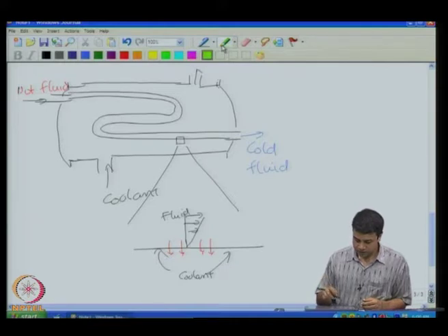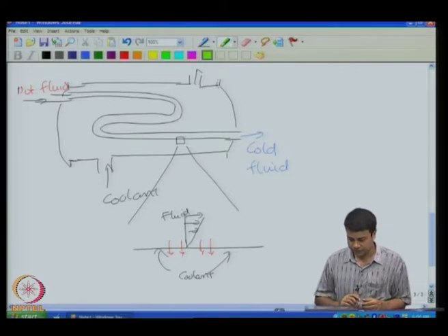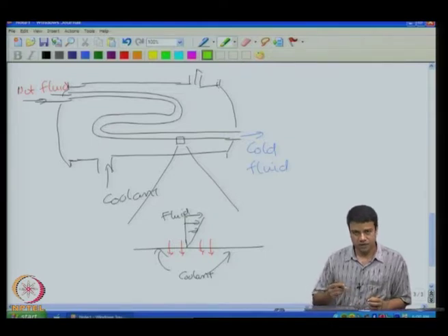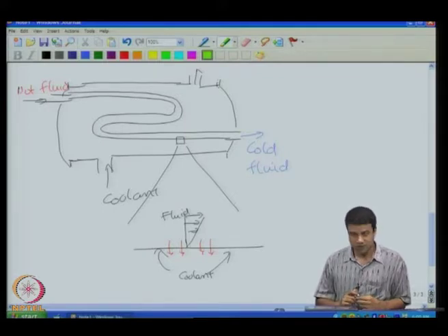And in order to ensure that the temperature is the desired value at the outlet, one has to make sure that in each patch of tube the amount of heat that is transferred is sufficient, so that cumulatively the amount of heat transferred is going to be the desired value. Now, the amount of heat transferred will of course depend upon the temperature difference between the shell and tube side, that itself is varying with position. It will depend upon the speed with which the fluid is flowing through. And it is also going to depend upon the length of the tube. Naively, one may think that it is best to have as long a tube as possible, because the longer the tube, the more heat is transferred, and so therefore you can get a much higher transfer rate.